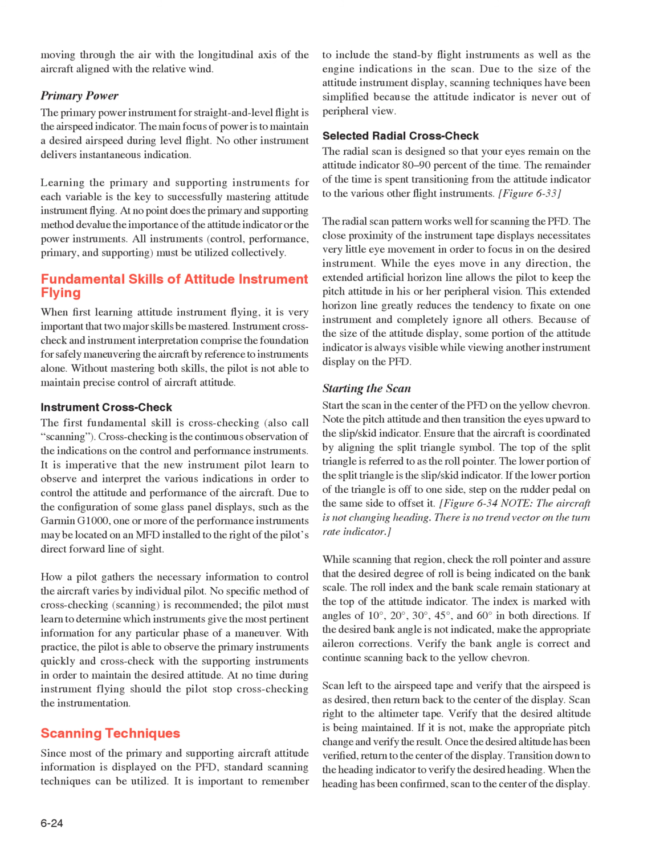Learning the primary and supporting instruments for each variable is the key to successfully mastering attitude instrument flying. At no point does the primary and supporting method devalue the importance of the attitude indicator or the power instruments. All instruments, control, performance, primary and supporting, must be utilized collectively.